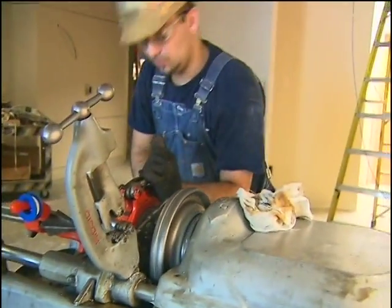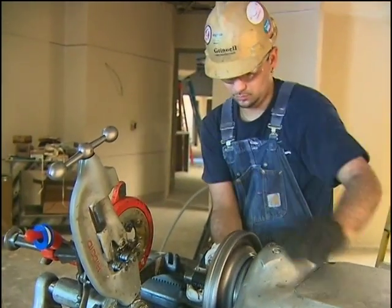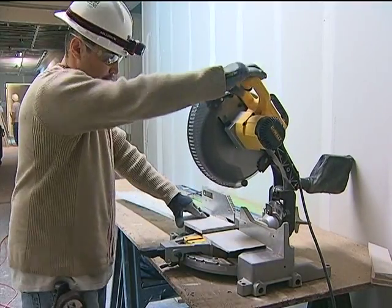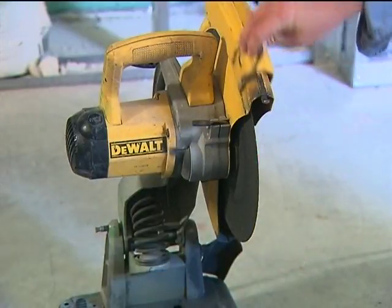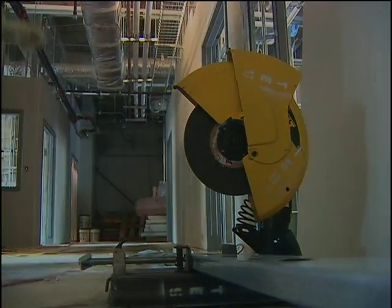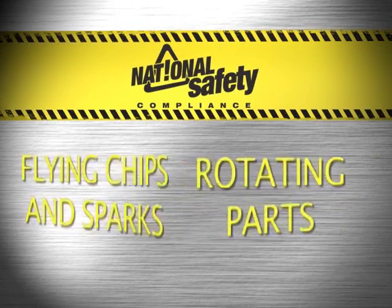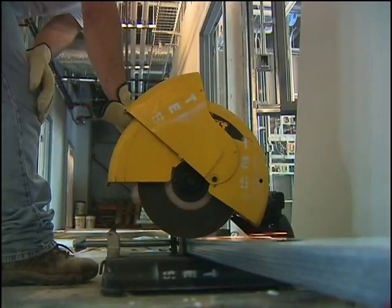Belts, gears, shafts, pulleys, drums, flywheels, chains, or other reciprocating, rotating, or moving parts of tools and equipment must be guarded if such parts are exposed to contact by an operator or other personnel. Machine guards, as appropriate, must be provided to protect the operator and others from the following: the point of operation, in-running nip points, rotating parts, and flying chips and sparks. Never remove or disable a guard from a tool.